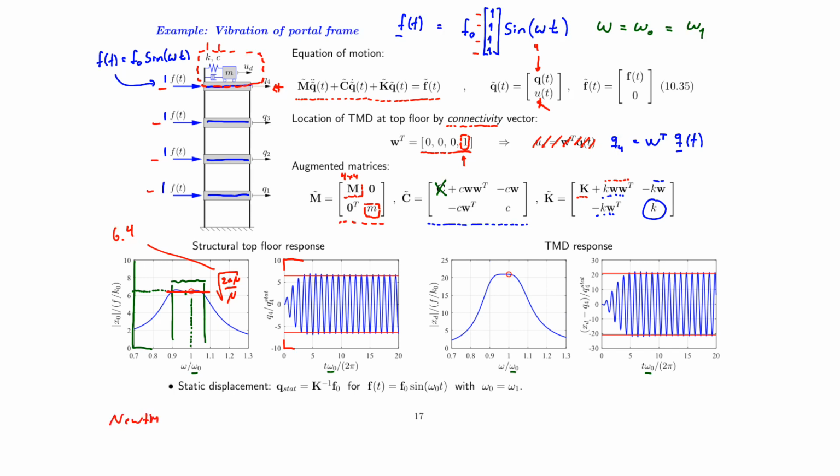Let's just start over. Nathan Newmark was his name, and I use this for my time simulation. And I need to use Newmark simulation or some other kind of time integration procedure, because modal analysis is not applicable anymore, because the presence of the damping and the stiffness will violate my orthogonality conditions.